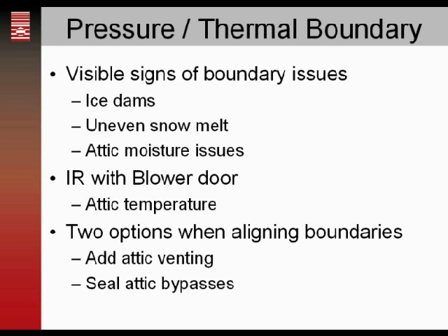The venting was essentially just venting out the warm air that was leaking into the attic and not drawing any outdoor air in from the low roof vents. So we left the attic hatch off, left the blower door running for a while. That cooled the attic down enough, put the attic hatch back in place, and were able to find the bypasses using the infrared camera. So what happened was the pressure boundary was the roof rather than the attic ceiling.